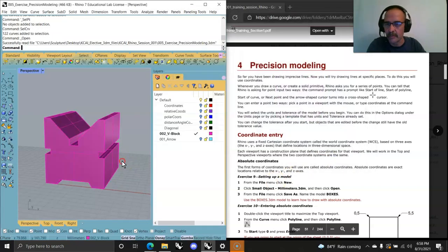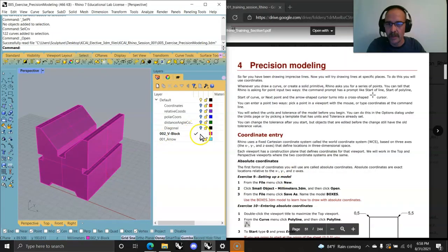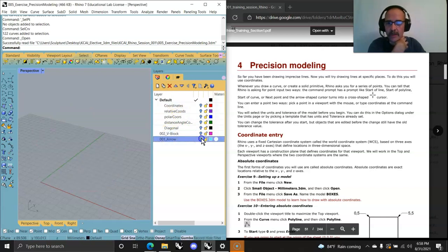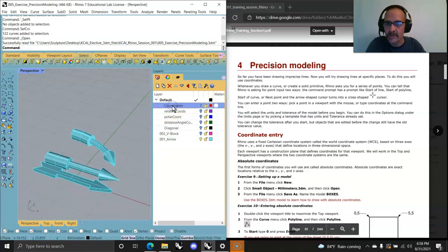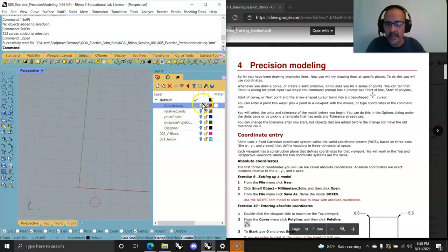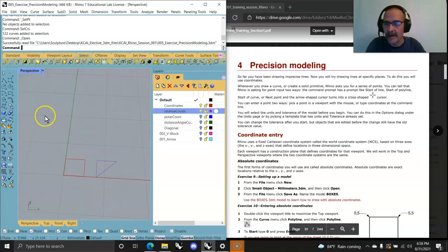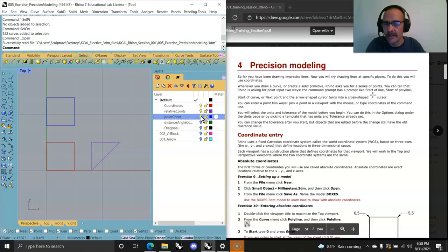And you can see I ended up making a pretty nice little structure here, the Vblock, that I actually categorized. I'm going to go back to my default and take the Vblock off. I also made a very bendy, wonderful little shape of these things. And then I also showed how to work with these squares to generate this by coordinates, to generate this one by, we'll go into top view, this will make more sense. How to make relative coordinates to build that one, how to build polar coordinates this way with angles, and how to use distant angle coordinates to make this.